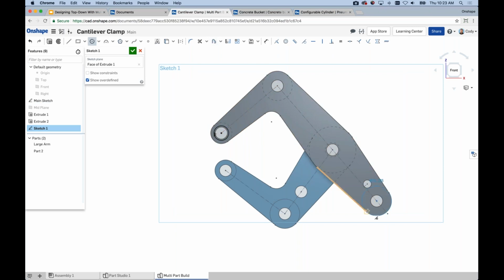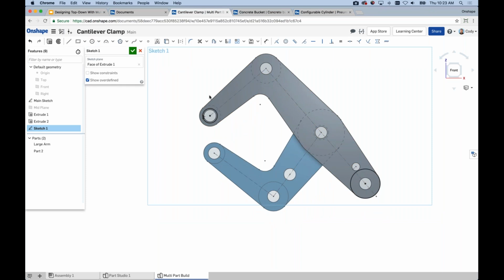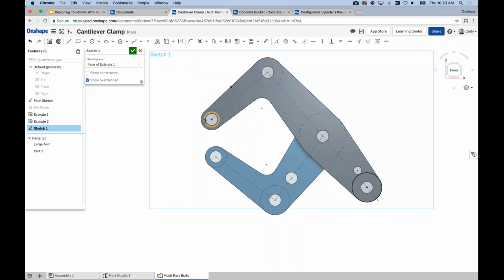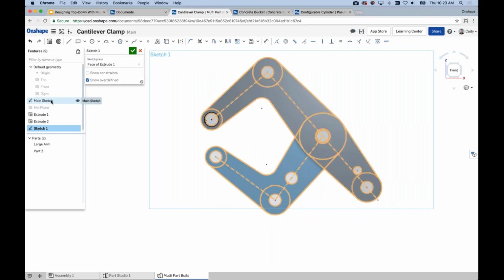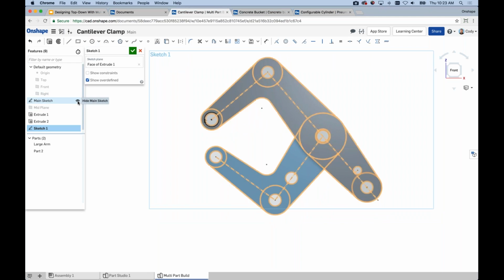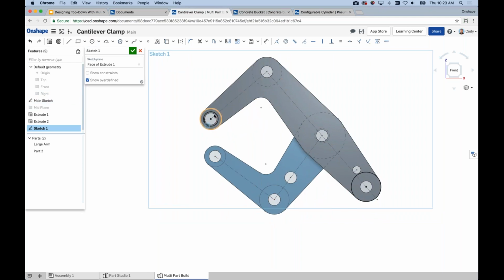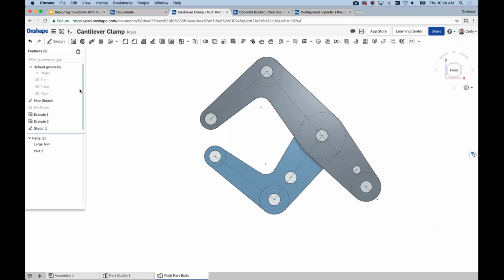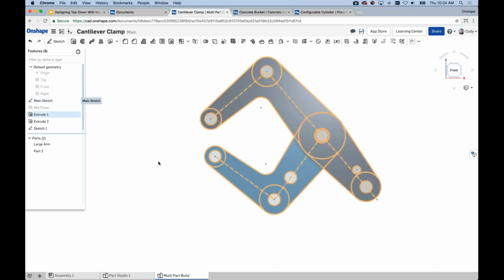My key point that I would stress here is even this new sketch that I'm creating is still tied to the first sketch that we created, right? Notice that the first sketch is showing. I have it set to show, and all of the sketch geometry that I'm creating now is referencing that original sketch, and that's what gives me that ability to control everything from this first sketch.